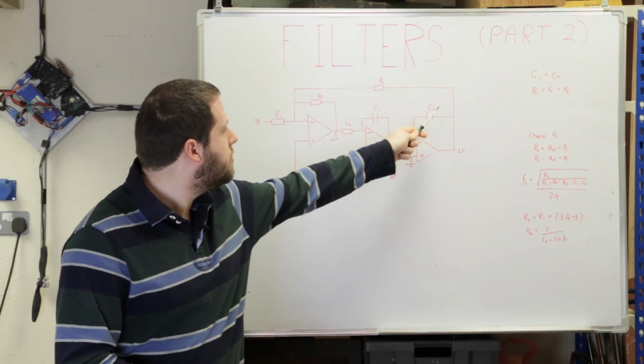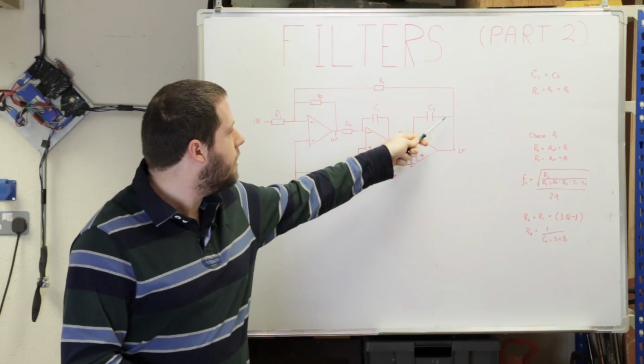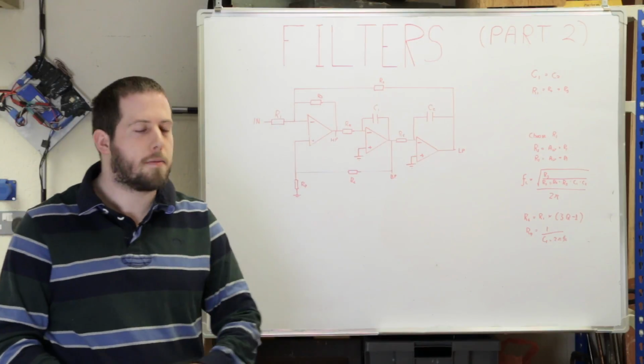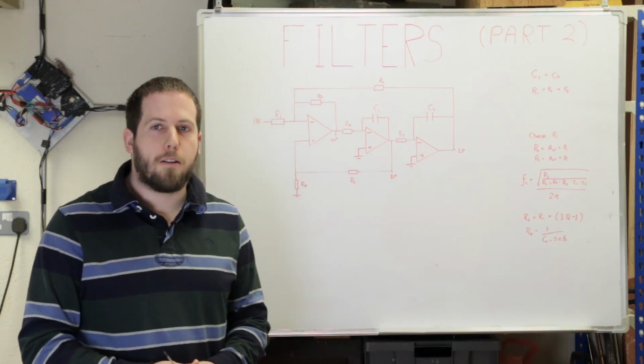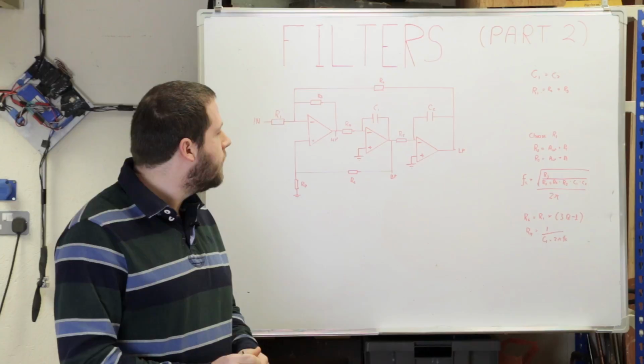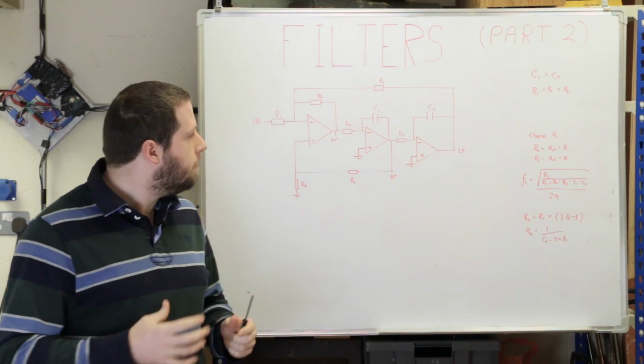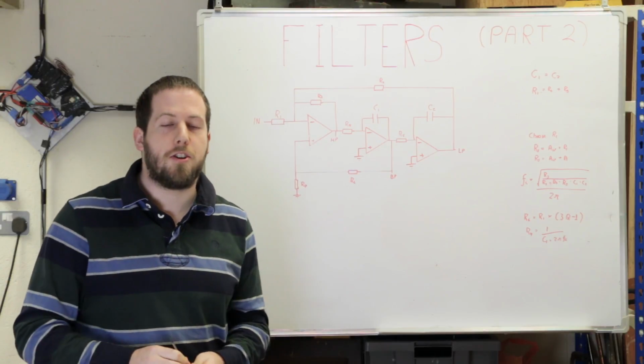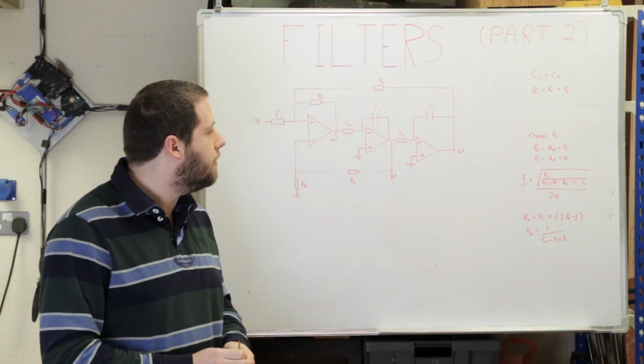So if you put some analog switches in here, you can turn on your 1 nanofarad capacitor, or your 10 nanofarad, or your 100 nanofarad capacitor, and that's going to expand your range quite widely. So this means you can make your resistor selection much less critical. It means you can get away with some slightly cheaper or slightly easier control options.